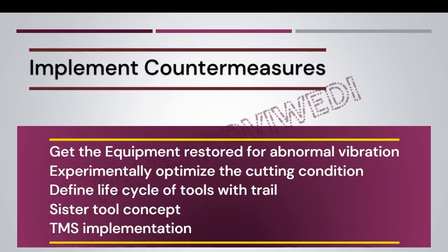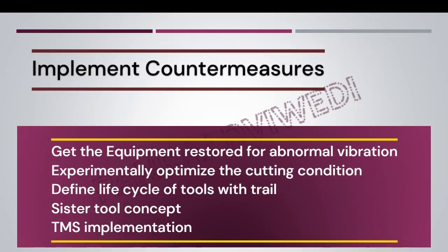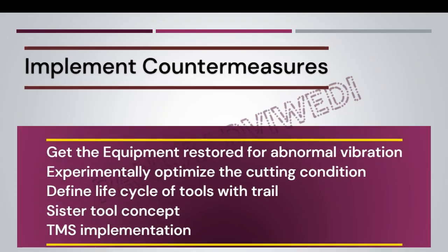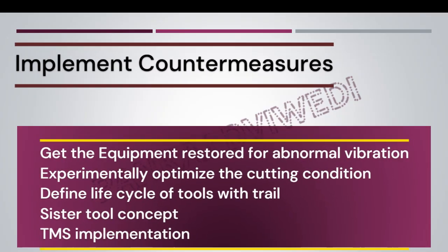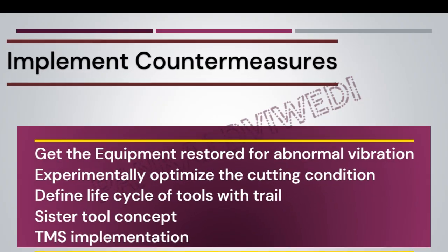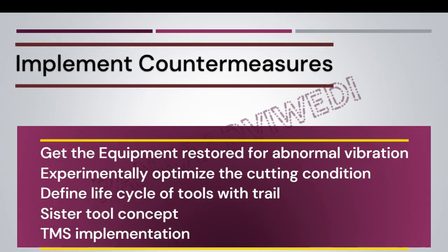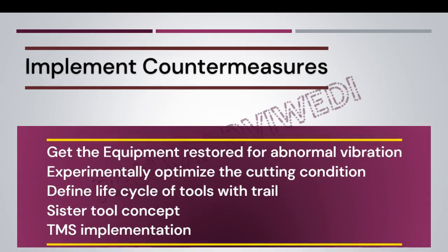Apart from this, nowadays machines have a facility of current measurement. You can link the motor current with the tool monitoring system. The machine can give an alarm when the current goes beyond a specific limit.